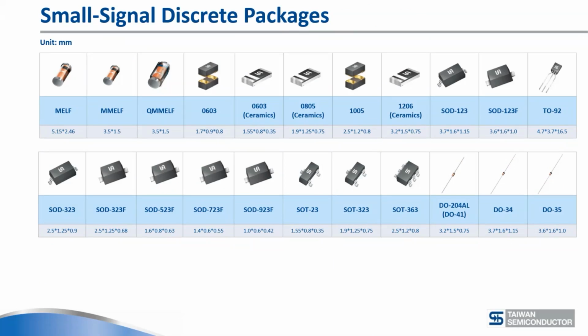Probably, some people like those because of the profiles. But frankly speaking, there will always be a mismatch in the temperature coefficient of ceramics and semiconductors, so they'll always have a more limited application space. Let's put it like that. The TO92 is really running on its last legs. That's really going. Then you have a bunch of other actual packages, but all the big packages going